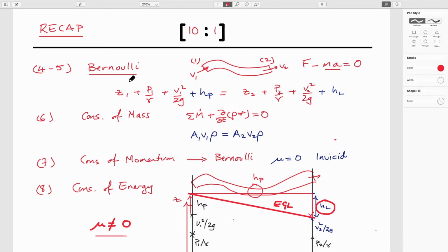And Bernoulli allows us to look at flows from upstream to downstream. It's really just a reformulation of Newton's second law, which allows us to account for the fact that fluids, when they're accelerated, have a resistance to acceleration, which is due to inertia. And when you stop them accelerating, for instance, you can apply forces onto structures like the truck being pulled behind the 747 engine, or whatever plane it was. So at stagnation, you get a force applied as a result of that.